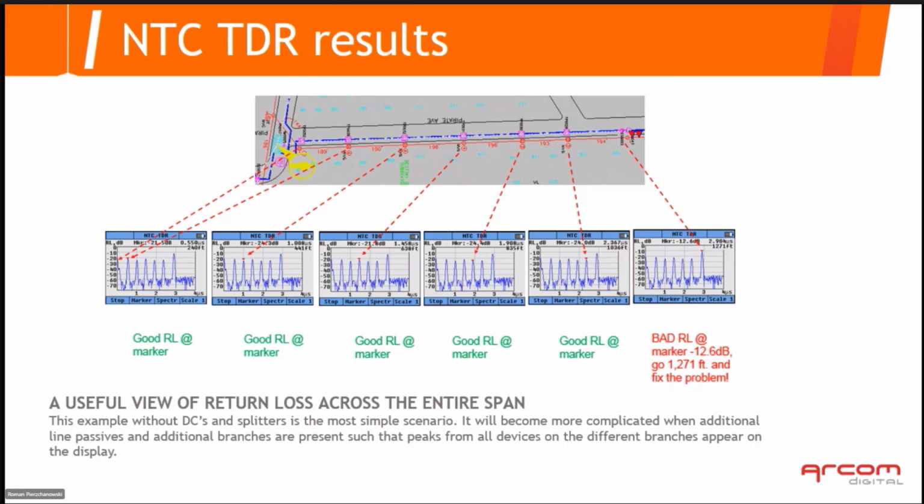Here is a record from a real situation experienced in the field. We were connected with a previous, smaller version of Quiver at the fiber node, and we scanned this stretch of cable plant. At the end of this line, there was a terminator which had only 12.6 dB return loss.